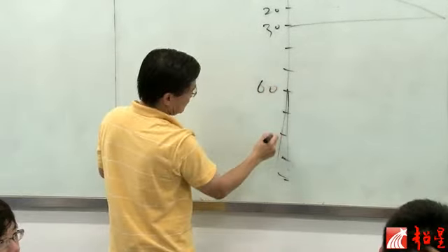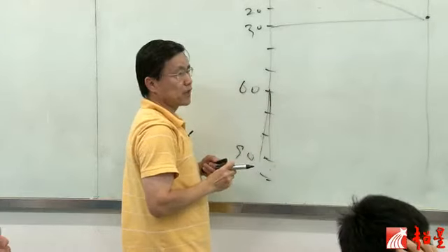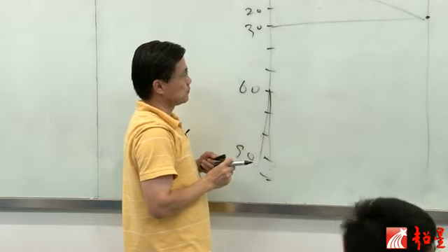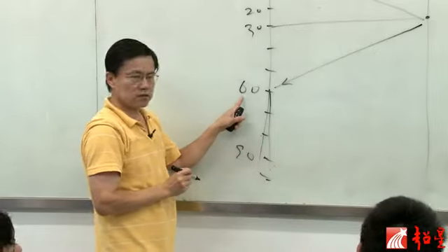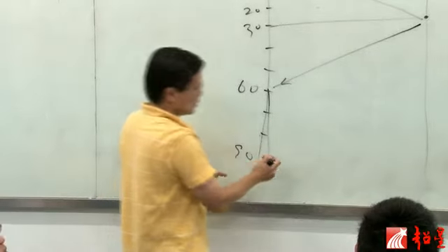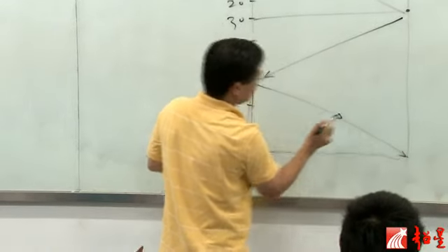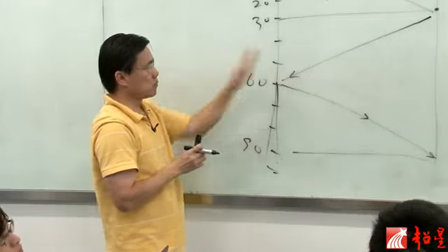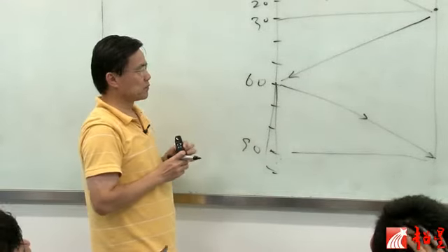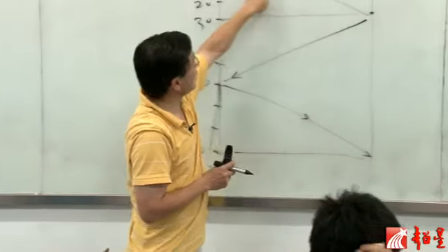The wave should hit the final load at 30 nanoseconds, and then it's going to be reflected back at 60 nanoseconds, and then it's going to go back and hit the load again at 90 nanoseconds. So the wave bounces back and forth. All right. So what is the initial wave?